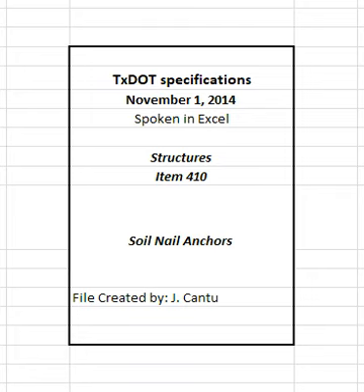Unless otherwise shown on the plans, the proof test nail acceptance criteria is: the total creep movement is less than 0.04 inches during the final 10 minutes reading increment. If movement exceeds this value, the engineer may require an additional hold period of up to 60 minutes with a maximum 0.08 inches total creep movement, including the movement from the original 10 minutes hold.